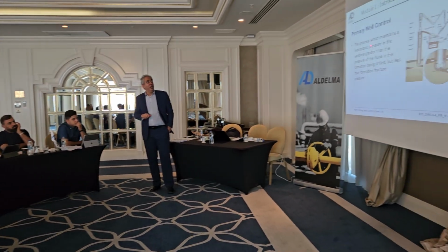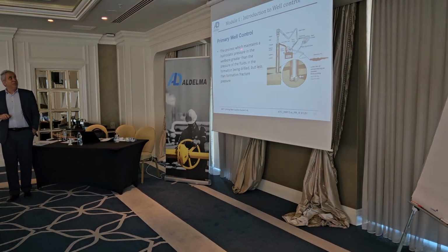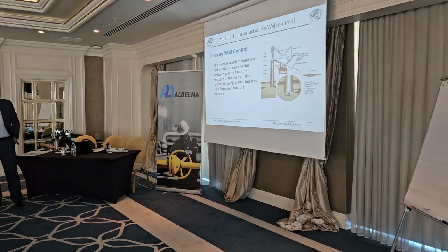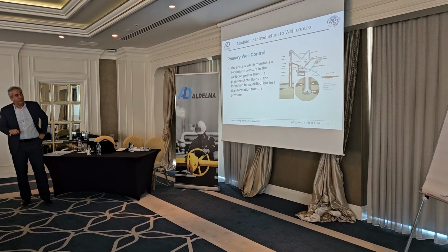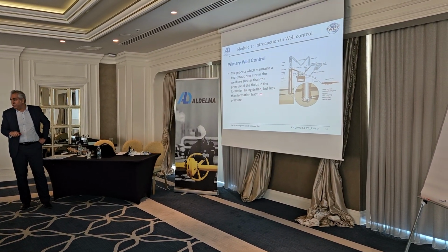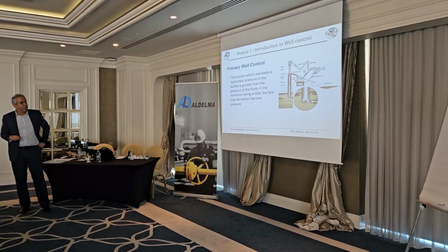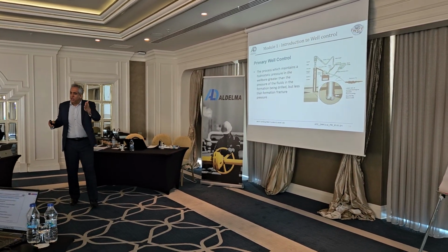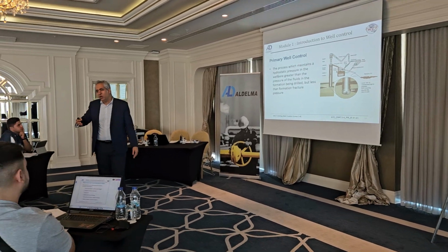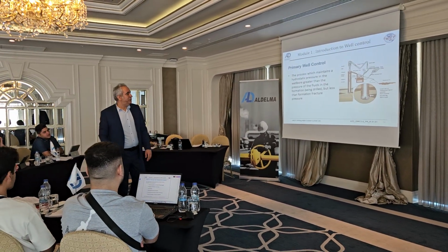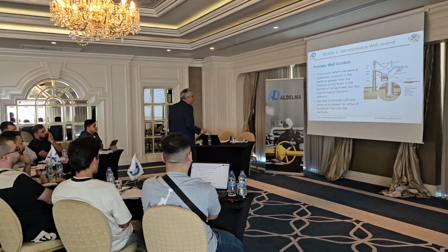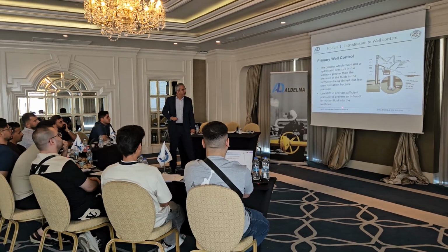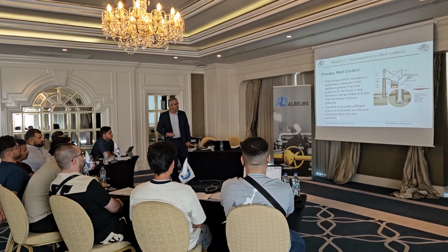Look at the primary, yeah. The process which maintains a hydrostatic pressure in the wellbore greater than the pressure of the fluids in the formation being drilled, but less than the formation fracture pressure. You need to be in the window, yeah? In the window, the lower limit is going to be pore pressure, the upper limit is going to be fracture. Use mud weight to provide sufficient pressure to prevent an influx of formation fluid into the wellbore.